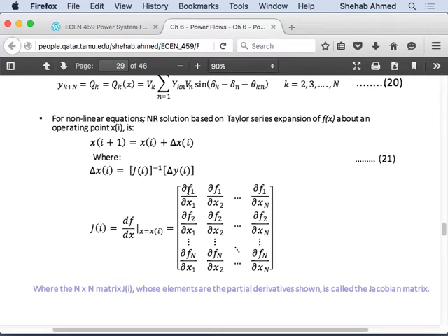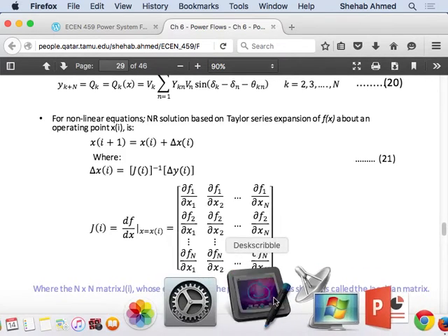But remember, for the slack bus, we don't have equations. We did not use the equations of the slack bus. We eliminated 2, so then it becomes an 8x8, because I eliminated 2 equations from the 10x10. At a PV bus, I can also use only one of the equations instead of 2, so I can eliminate one more. For the 4-bus system that we just did, we had one PV bus, 2 PQ buses, and a slack bus. So let's just do it for that specific system.